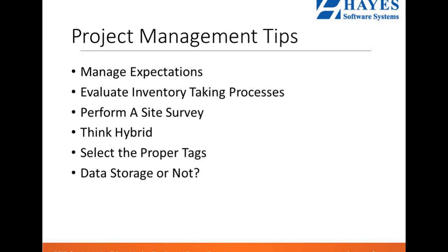Initially, one of the key advantages touted with RFID was the ability to store various data in the tag itself, making it available wherever the tag was. In reality, 90% or more of the applications using UHF Gen 2 tags will not require this feature. Why? Because storing additional data within a tag creates some troublesome issues, not the least of which is devising a reasonable security scheme to prevent unauthorized access to that data.